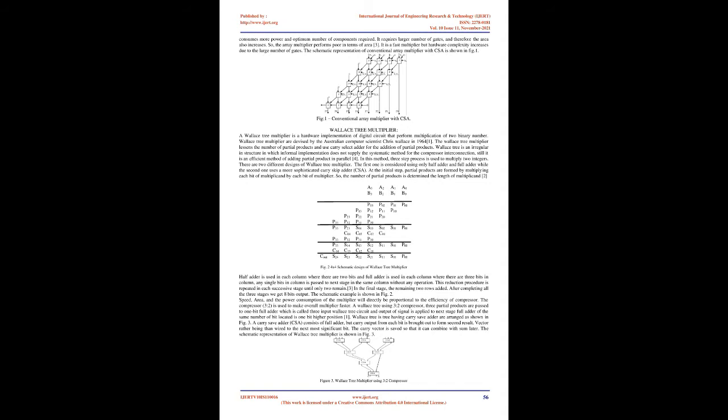Traditionally, the shift and add algorithm has been used to perform multiplication. However, it is not suitable for faster multiplication in VLSI because it requires a greater number of adder units, which leads to higher delay in performing the multiplication operation. Some traditional approaches for speeding up multiplication are reducing the number of partial products by using multi-bit compressors. Multipliers can be classified into 2 categories, namely, serial and parallel multipliers.